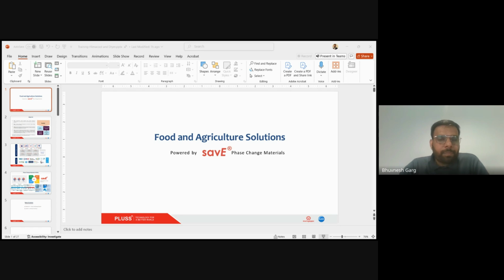There are different chemistries of PCMs. One is hydrated salt, where the PCMs are made of water and different kinds of salts. You might be knowing about one very common salt, NaCl. Like that, there are other kinds of salts like magnesium chloride, which are used in making some compositions of PCM. Then there is organic mixture, which is fatty acid based, like plant extracts or petroleum based products, which melt and freeze at a particular temperature.